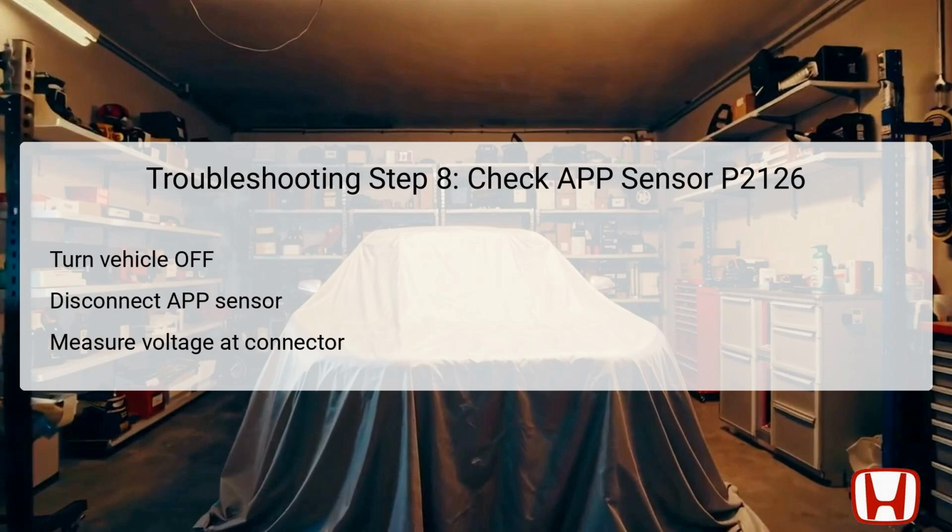Start with the vehicle in the off mode and completely disconnect the APP sensor 6P connector. Afterward, switch the vehicle to the on mode and measure the voltage between the specified test points of the connector, verifying that you are receiving around 5.0 volts. If voltage levels are met satisfactorily, this indicates that the APP sensor is potentially faulty and should be replaced. Should the reading be inadequate, further investigation will guide you to check additional systems before arriving at a conclusion.